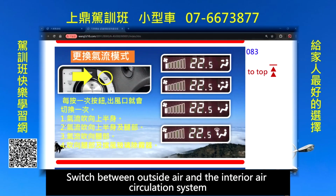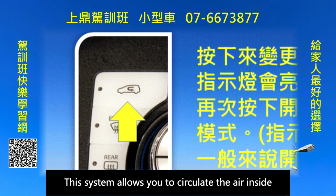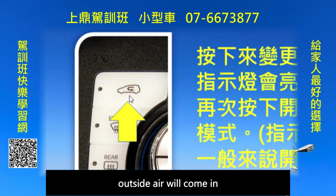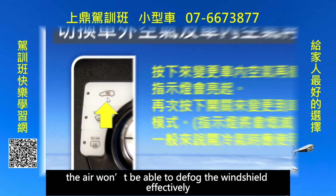Switch between outside air and the interior air circulation system. This system allows you to circulate the air inside. After you press the button, because you're using the air conditioning, you don't want outside air to come in. This way, the air conditioning will be cooler. If you turn it off, outside air will come in. Consequently, the air won't be able to defog the windshield effectively.